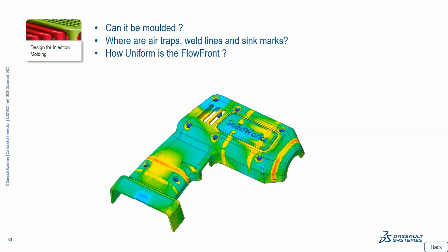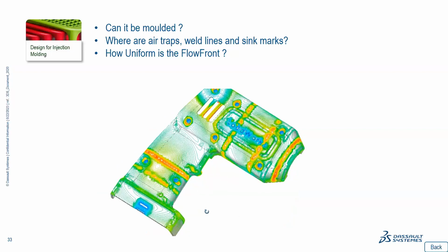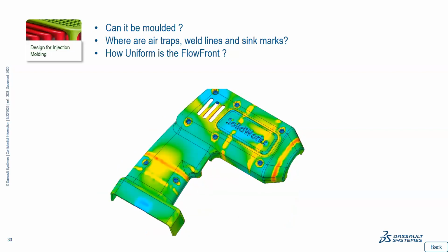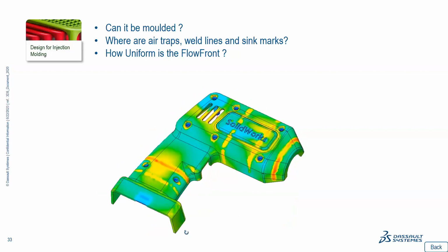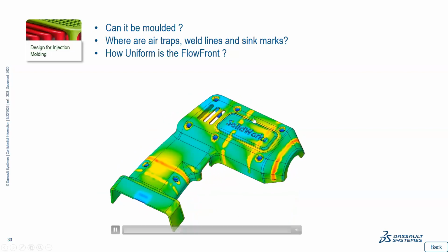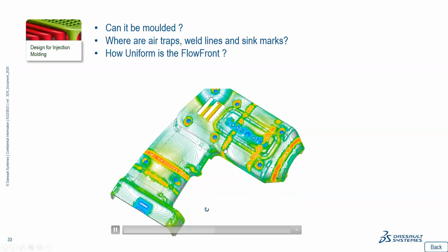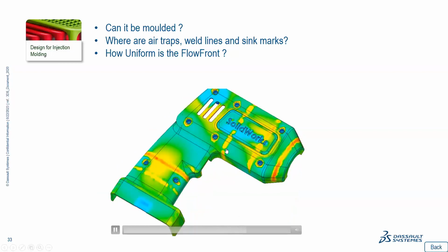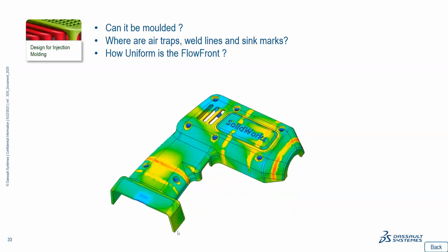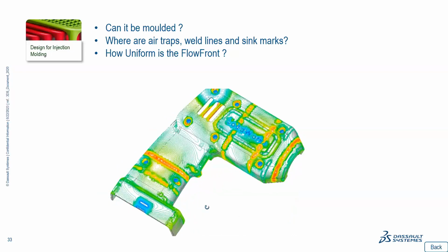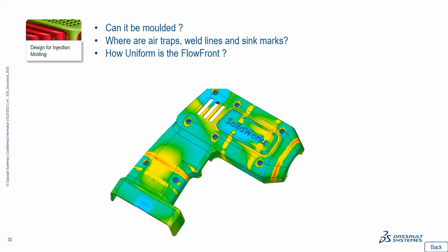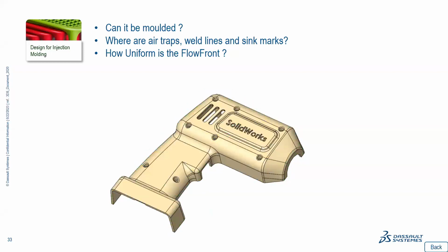And here's another thing you can see when you're doing plastic injection: when the plastic cools, it will retract. So you will have some marks on the plastics. And the thicker your part is, or where you have more material, the more it will shrink, because you have more material to shrink. So it's where you have the bigger marks on your plastic. We call that, how do we call that? I don't remember the term. And this is something you really want to anticipate.